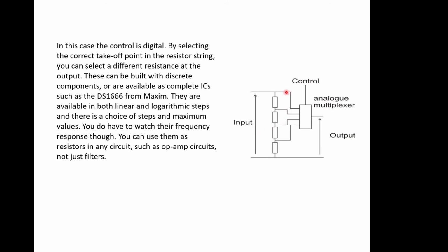The problem that you do get with them, which they don't advertise, is that although they are mainly a bunch of resistors, there's always going to be some stray, parasitic capacitance associated with these resistors, and then you've got an RC time constant, and that leads to a frequency response. So these are not great for high frequency systems. They've been designed to be good at audio, so anything up to about 20, 30, 40 kilohertz they'll be okay for. But after that you have to be careful, because their signals will roll off with frequency, and it doesn't tell you that in the datasheet. You have to find that out the hard way.